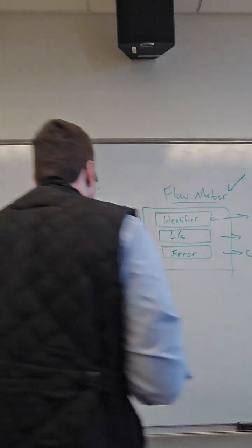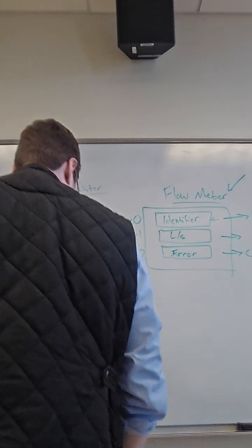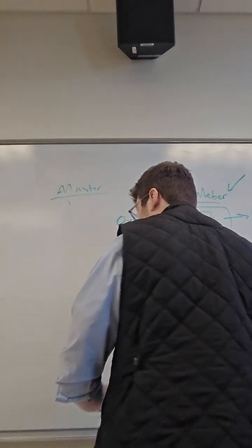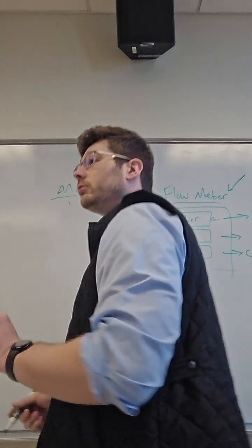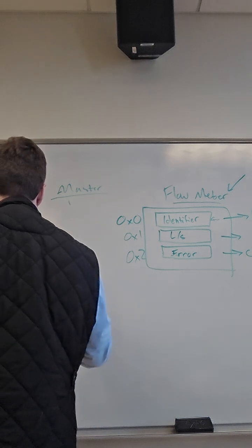Okay, so the way that this is actually done is with codes and the actual data. These codes, 1, 2, 5, 15, 3, 4, and so on, are how we actually get the receiver to divulge the information we want. Remember, at the end of the day, especially for serial RTU, with the 3 copper lines, all we're doing is wiggling those lines up and down.